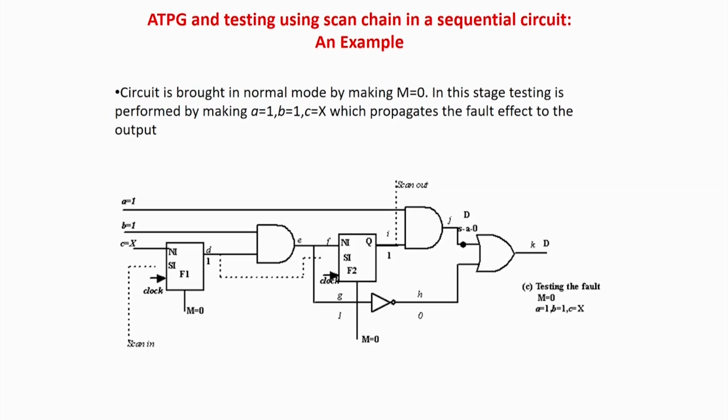Secondly, about the scan chain. If you make a very long scan chain, the time to insert the test pattern in the shift register will be very, very high. So what can I do? Can I partition the scan chain? Can I put some of the flops in partial scan mode, meaning some of the flops will be in scan and some will be left as they are, so that at least some area is saved, and at the same time I can have less time to push in the test patterns, because now instead of one chain I will have many parallel chains. But many parallel chains mean at the same time many pinouts. So I cannot have 100 parallel scan chains. So how will I make a trade off?